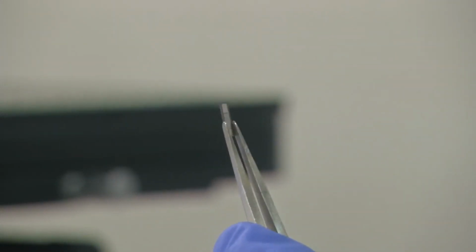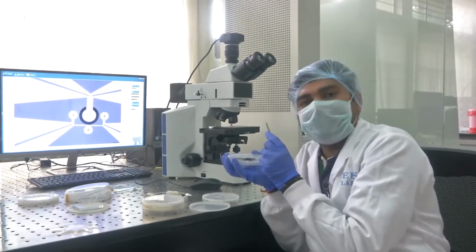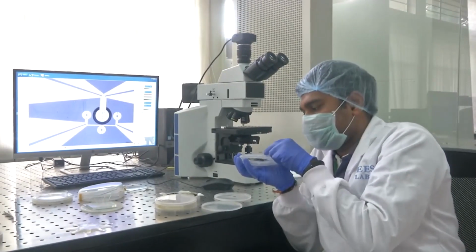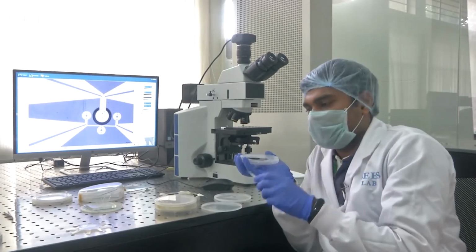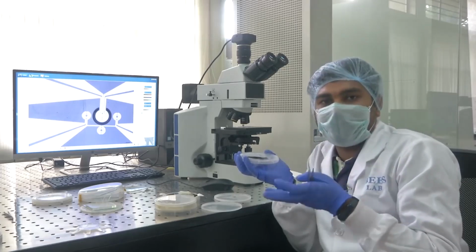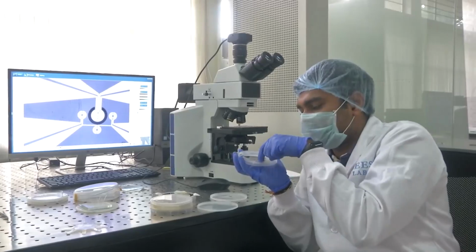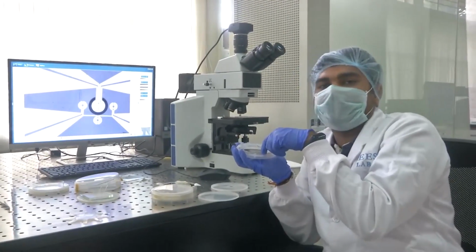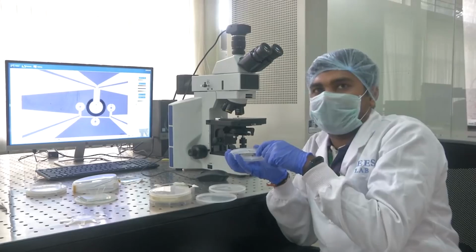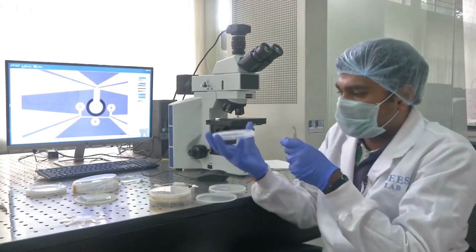Now how do you handle such things to make intelligent systems? For that you need to use a technique called wire bonding. So you can increase the area that you have to work with by bonding these contacts of the sensors onto a PCB kind of structure using a technique called wire bonding, and then you can take the contact pads from there. I will show you this same sensor that has been wire bonded onto a substrate.